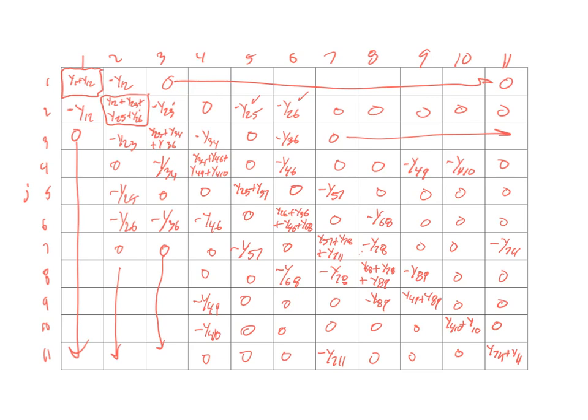Okay, so this is the completed Y-bus matrix for both the positive and negative sequence diagrams. And the only thing that would change here if your negative sequence impedances were different is if you had different numbers. So in that case, and what I did for doing this sort of generically, is if I had a y12, that's the impedance between 1 and 2, but I might either put an underscore -1 to show that's the positive sequence, or if I want to be lazy, I might just show with a 1 added onto it to show that's y1 to 2 with a positive sequence.